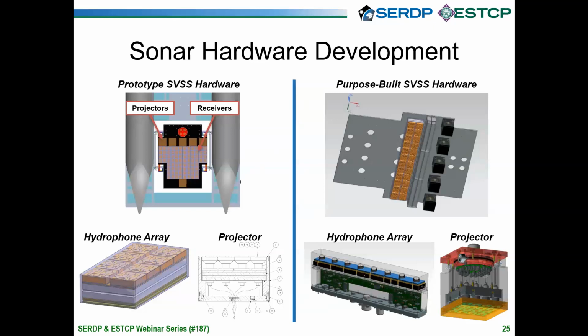Along those lines, we then tried to leverage existing hardware that's here at ARL Penn State to the greatest extent possible. So we started out with these 8-channel hydrophone arrays shown here in a 2x4 configuration. These hydrophone arrays had been built for another program, and so we already had access to these. And in some sense, we treat them almost like Legos, right? These are devices that exist for us. We can reconfigure them on an array plate on this pontoon boat. And so we have 10 of these 8-channel hydrophone modules, and we arranged them in this T shape, giving us an 80-channel receive array.